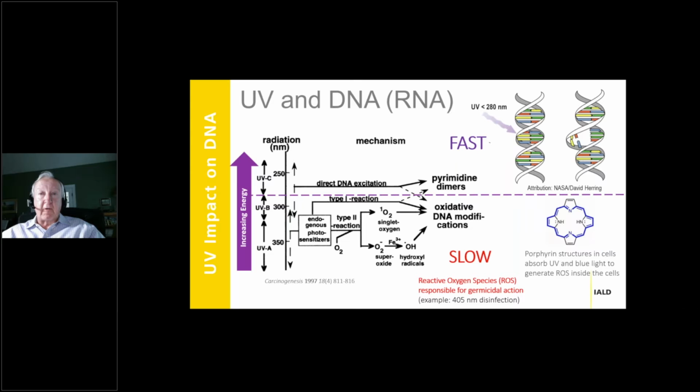is in a very special environment, there are no reactive oxygen generating chemicals around to absorb the light and generate reactive oxygen species to attack the virus. So for all intents and purposes, UVB, UVA, and 405 are not really worthwhile to consider for virus disinfection, but they can work well, albeit slowly, for bacteria and similar kinds of cellular pathogens. Now let's take a look more closely at UVC wavelengths and dose considerations for germicidal systems.